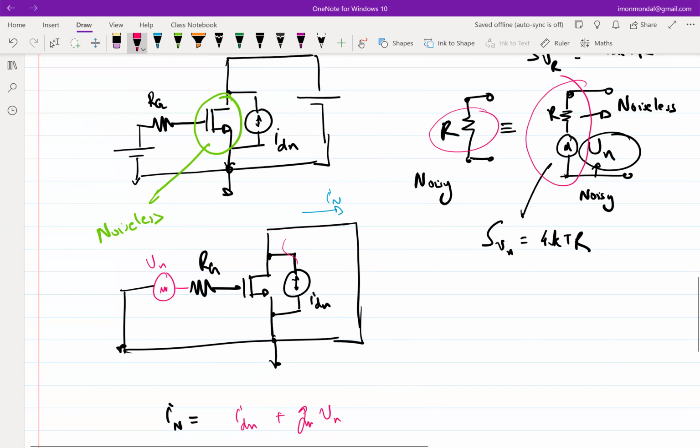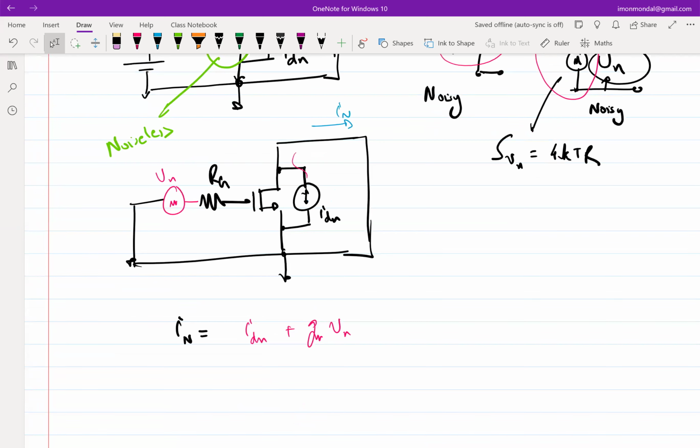So in principle, even though this is happening, at 0th order I can say that this is uncorrelated, but in principle it's not, because if something happens at the gate, obviously it is going to affect the channel also, right? But for all practical purposes, I can still keep it as uncorrelated. So I need not bother about the sign of whether I am doing plus or minus. You can as well keep plus, as well keep minus, because they are not going to cancel each other with respect to time, right?